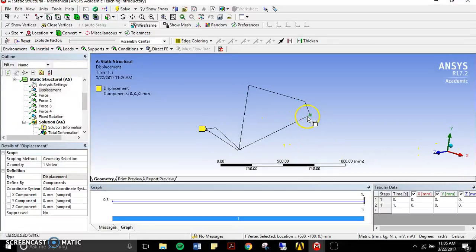Okay, now z-wise rotations. Z-wise rotations should not be a huge problem. Hopefully, they'll all be reacted by the two displacement reactions of the wheels. At least that's the idea. So we can probably put our z-wise rotation there. Okay, cool. Currently, we have a system that is not constrained at all in y rotations. That's a problem, because it will just spin around on the y-axis. So we can probably put it there.